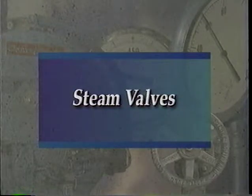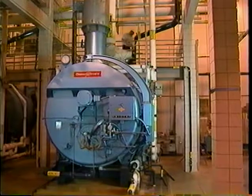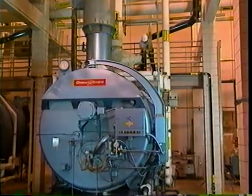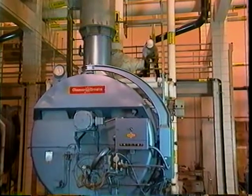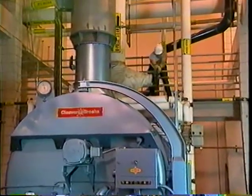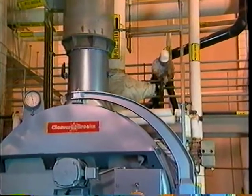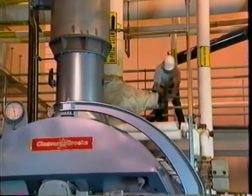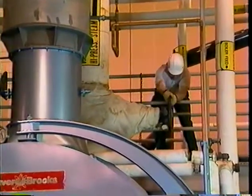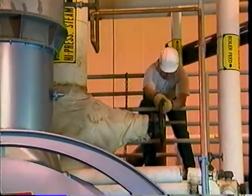Steam valves. Steam valves commonly used include a gate valve used for the main steam stop valve and the globe valve. The main steam stop valve cuts the boiler in on line, allowing steam to flow from the boiler, or takes it offline. This is an outside stem and yoke, or OS&Y valve.